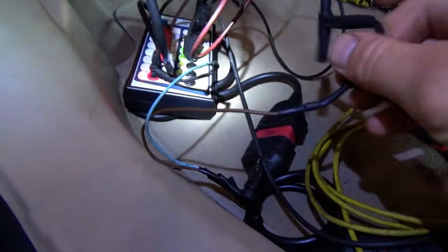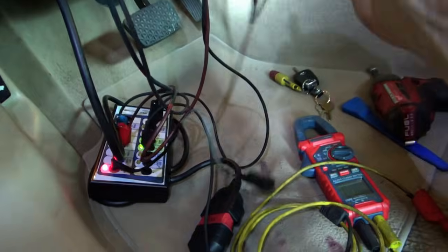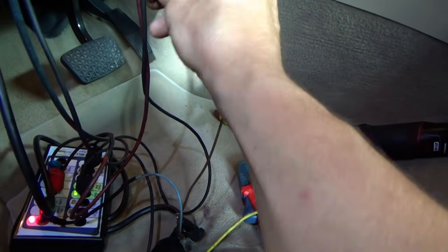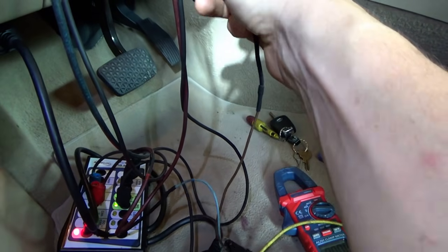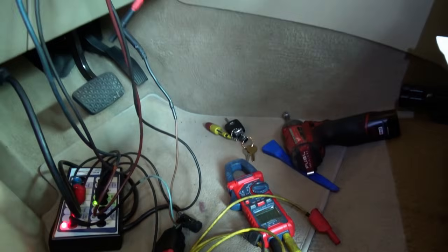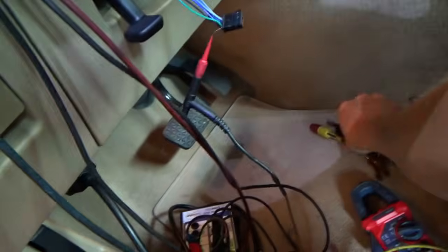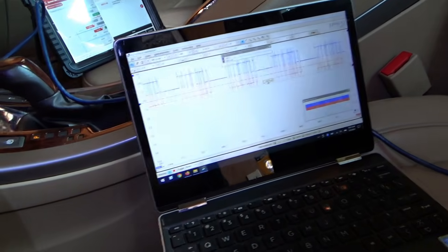So let's do that quick check. Okay, so little baby test light, 300 milliamps from battery positive. If it finds a ground, see it lights up. So we're going to attach this right to the green wire. We'll see what happens. Now, no, we're not going to cook anything. That is a 12 volt feed, so we're just making it 12 volts. Test light's not lighting up. Let's turn the key on. And we'll see if the ABS module starts talking to anything.